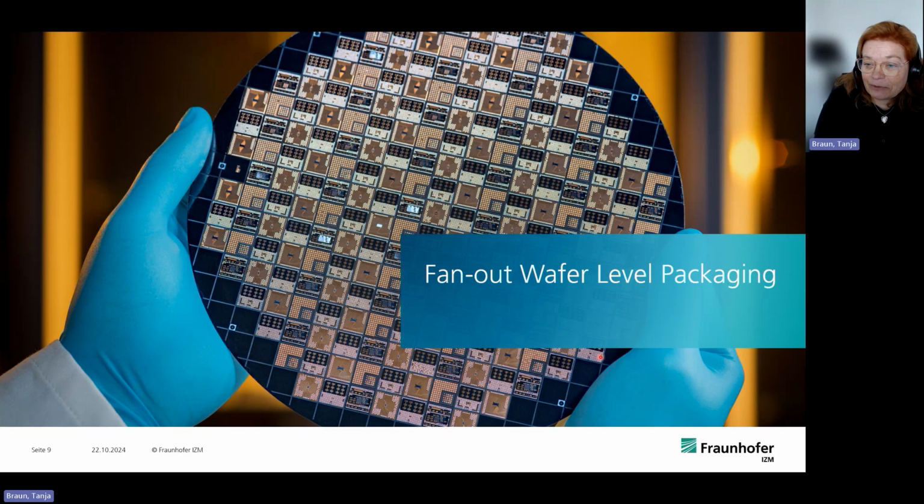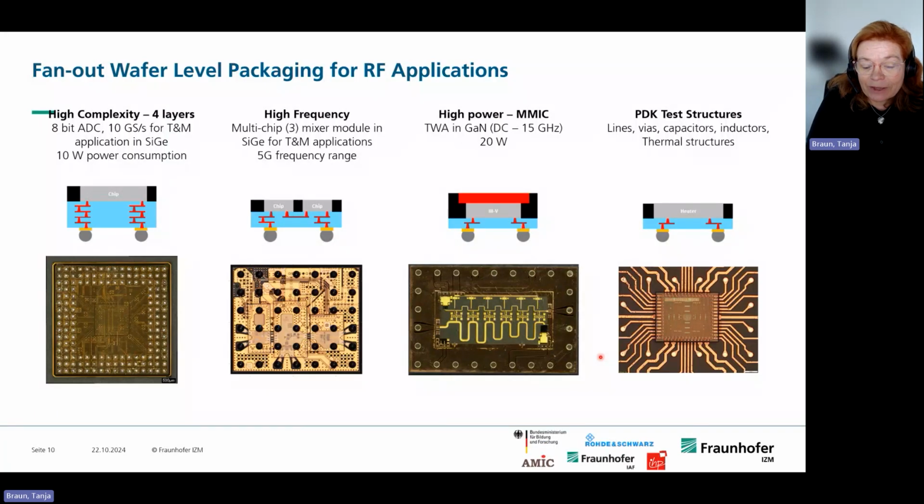Yeah, let's start with wafer level fan-out packaging. I would like to show one slide. I think application-wise we're doing a lot of high-frequency applications because fan-out is a very nice approach there: no substrates and very short interconnects, because you only have that metallized RDL line from chip to chip, for example, and the connection is a microwire. So there is no bump, no solder interconnect included in the package, and this is really nice for RF applications. And you see a bit the different topics we are working on at the moment.